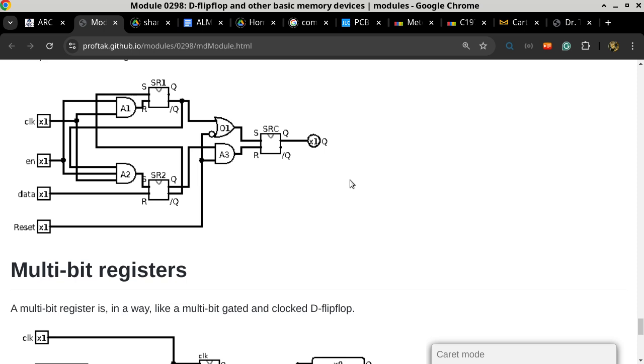So the watchdog chip is also responsible for looking at the supply voltage to the chips. If it is below a certain point, it will hold the reset, like the reset pin that we see here. It will assert the reset for a certain period of time until the voltage is stabilized. Then it will release the reset, and then things can start to happen at that point. Is that okay? That's the concept behind how computers start up when you first power up the computer.